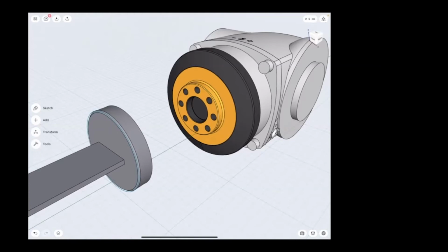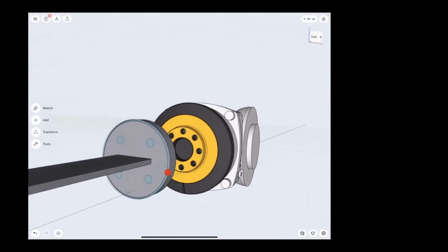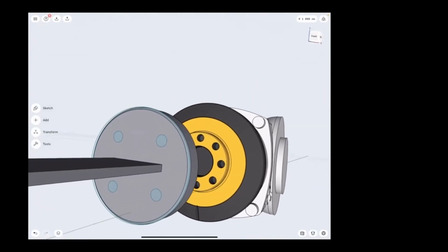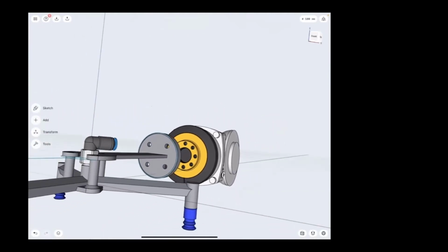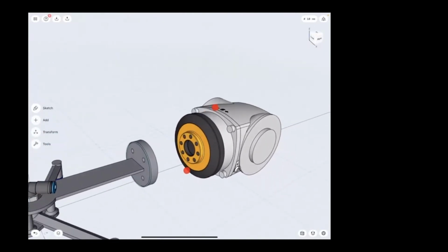Holes will be created by simply just selecting them and projecting those to the face of the lastly created part. And after I have the 4 cross sections there, I can simply just select them and extrude away the material to have the holes for the screws, and I can assemble the robotic arm with my gripper pieces.